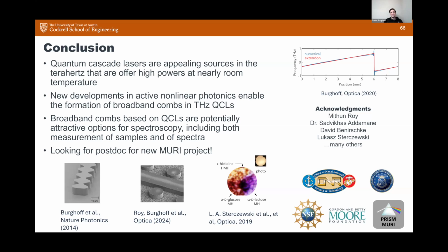Yes. Well, actually, these kinds of combs do exist. They're called harmonic state combs, and I didn't really get into them. It's another mode of operation that these QCL combs sometimes fall into. Basically, it's a mode of operation where the laser decides to skip every nth line. You can do this through a number of techniques. Sometimes it just happens spontaneously. You can also add defects to a cavity in order to do this. Actually, my first terahertz QCL combs had this behavior as well.